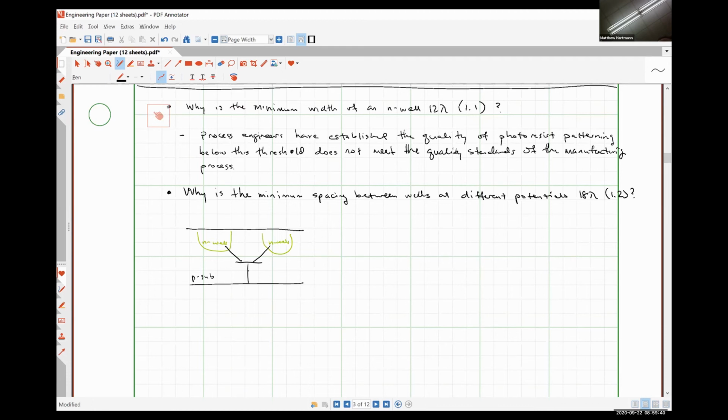Because if there's a potential difference, we should see that there's an electric field. Let's say that this guy is at V high and this guy is at V low. We're going to have an electric field in this direction, which is going to try to conduct across, I'm trying to remember what the right term is, maybe it is a channel still in a BJT. It's been a really long time since I've dealt with BJTs. But anyway, increasing that length makes it much, much harder for that parasitic BJT to accidentally turn on and influence the behavior of the system.